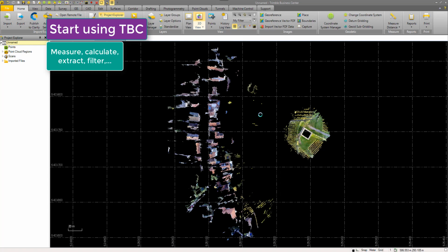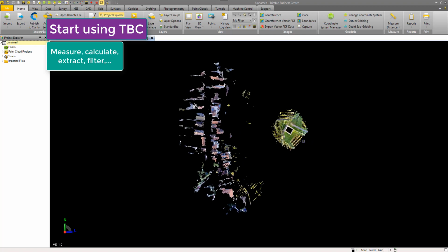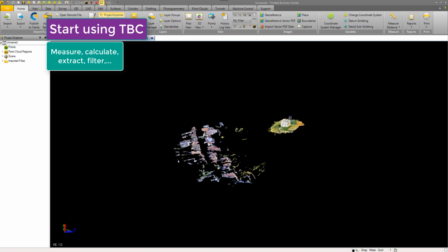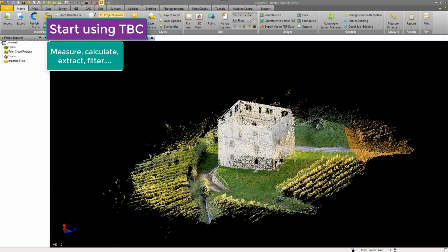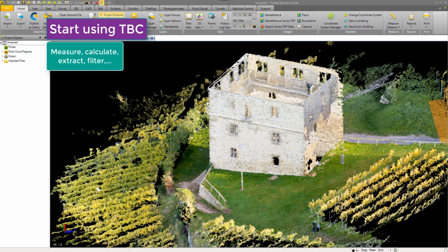And then we can rotate our view and take a look at the data from a perspective part. So here with the right mouse button we can pan, and with the left mouse button we could have selected, well, not a good idea, and with the middle mouse button I assume, yes, here we can rotate the data.